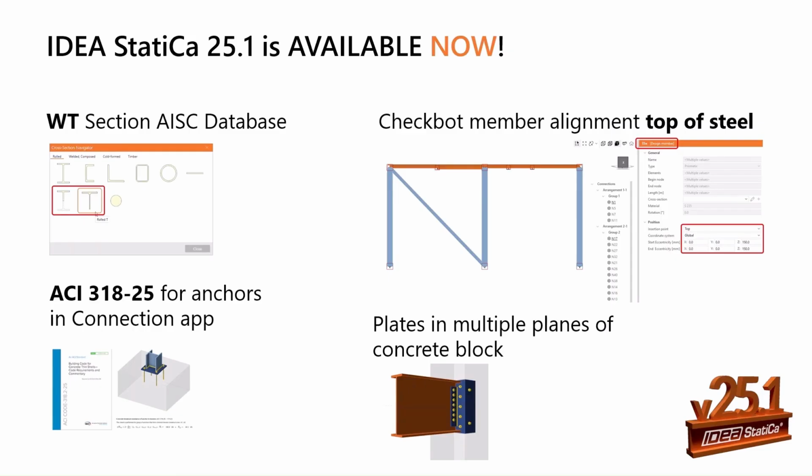And lastly, we also have a new feature where now you can introduce plates in multiple planes of the concrete block. We have had some instances before where users wanted to create things such as corner or edge base plate connections that require multiple plates in different planes. This was not a possibility, but now with 25.1, you can take advantage of this new feature.